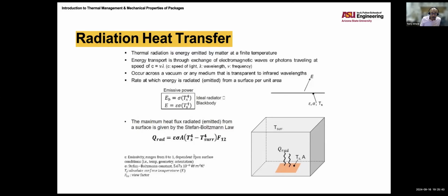So now we want the thermal resistance from the junction to the ambient, which is the temperature difference between the junction and the ambient divided by the power. This thermal resistance will be the sum of all the resistances. If I look at the schematic, they're all in series, so we can just take the linear sum.